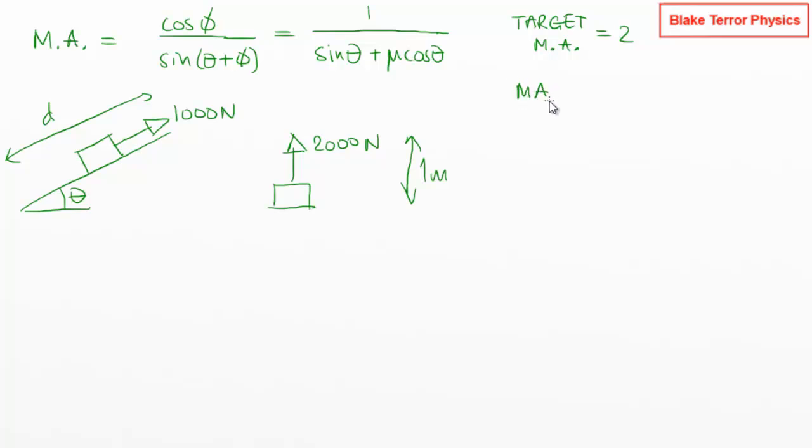So our MA max is going to be, well, we know we've got maximum mechanical advantage when we've got the lowest possible slope, because the smaller the incline, the greater the distance we're applying our force through, and the greater the distance we apply the force through, the lower the force has to be. So that's a chain: we reduce the angle, so the length of the slope goes up, so our force drops because we're multiplying the force by the distance.